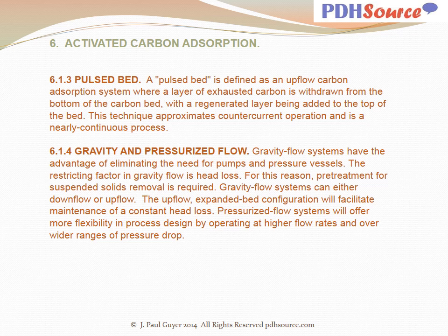Gravity flow systems have the advantage of eliminating the need for pumps and pressure vessels. The restricting factor in gravity flow is head loss. For this reason, pretreatment for suspended solids removal is required. Gravity flow systems can either downflow or upflow. The upflow expanded bed configuration will facilitate maintenance of a constant head loss. Pressurized flow systems will offer more flexibility in process design by operating at higher flow rates and over wider ranges of pressure drop.